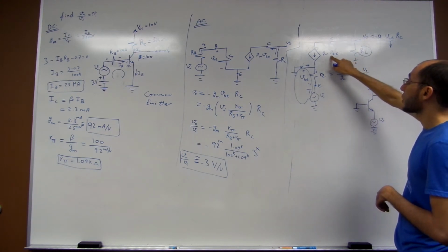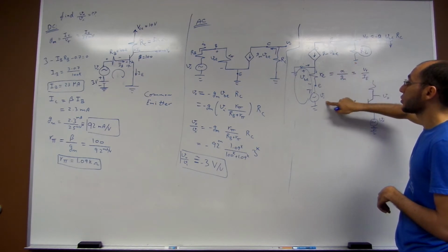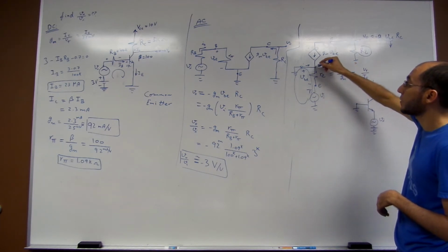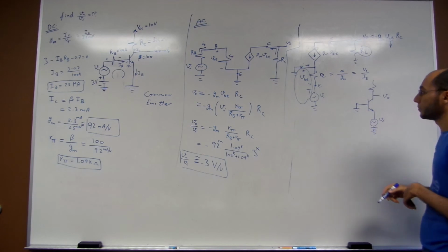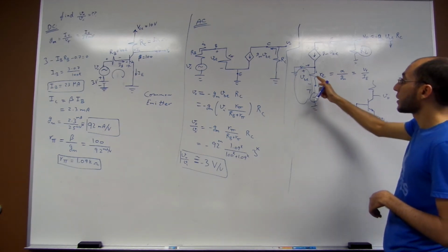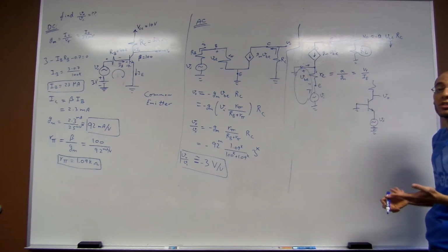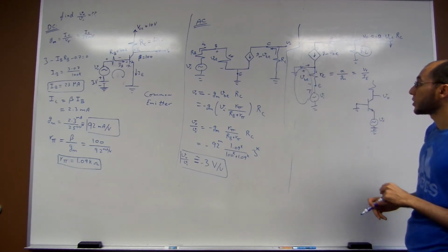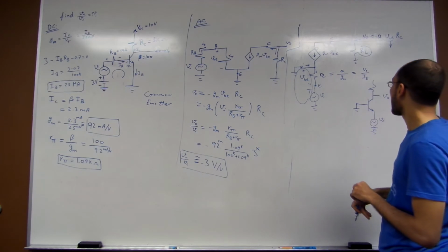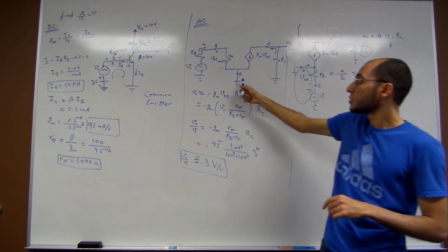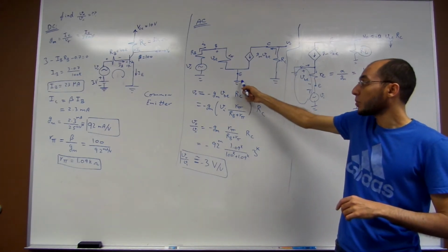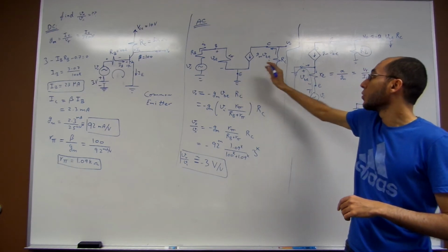And thus, you can obtain the value of VBE as a function of V input directly without the need to use any KCL, right? So whenever you have a common base, you need to use the T model, which makes the analysis much easier, right? And whenever you have a common emitter, use the pi model. Because the pi model has a common emitter.